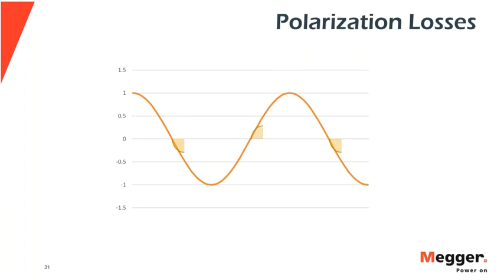So at really low frequencies, all the polarization processes that might happen in the material ultimately are going to finish. The movement in the material on an atomic and molecular level, all of that charge movement, will ultimately finish if you wait long enough. And at that point, the dominant contributor to loss is going to diminish and be representative just of conduction current, whatever leakage current is getting through that material.